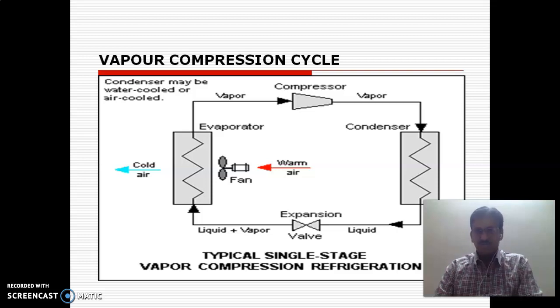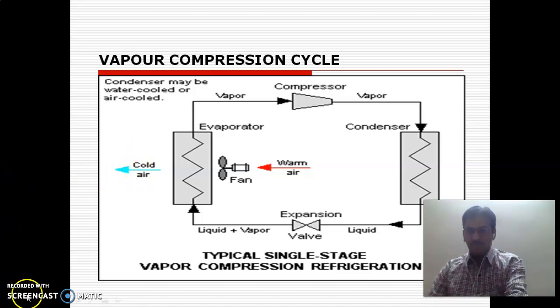So the difference you can measure is that the power required to run the compressor is more in the case of a water cooler, while in the case of an evaporative cooler we use only a small pump for circulating the water, which distributes the water into the evaporative pad, and the remaining components are absent.